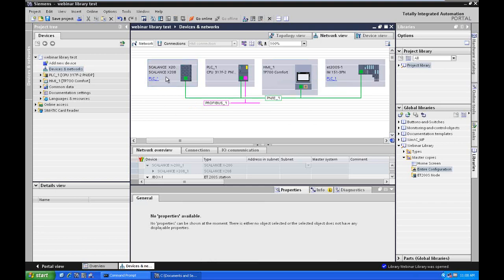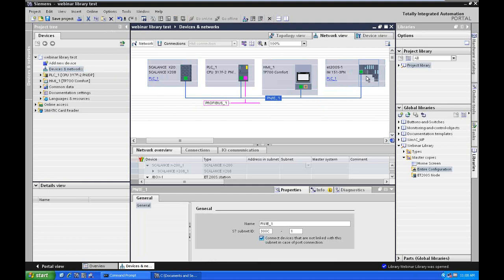So when I'm dealing with a Profinet network, before I perform a download, I go out and make sure my devices have the appropriate name assigned. I mentioned that each device has a Profinet name. So to do that, right-click on the Profinet network, select Assign Device Name.